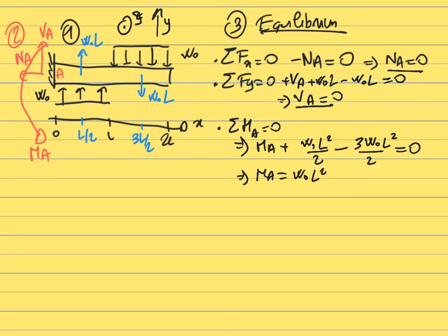Okay, and you can check that indeed this has the unit of a moment, since it's a distributed force. W naught has the unit of Newton per meter, times L squared, which is in meter squared. So you end up with something that has the unit of a moment, which is Newton meter.